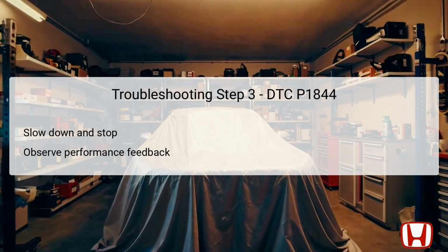Pay attention to the shift position indicator while performing this action. If there are no other issues impacting performance, the indicator should ideally not flash or display any alert warnings upon stopping. This observation is significant for diagnosing whether the DTC persists as part of the ongoing checks or has been resolved, further indicating the efficacy of the CVT's behavior and controls.